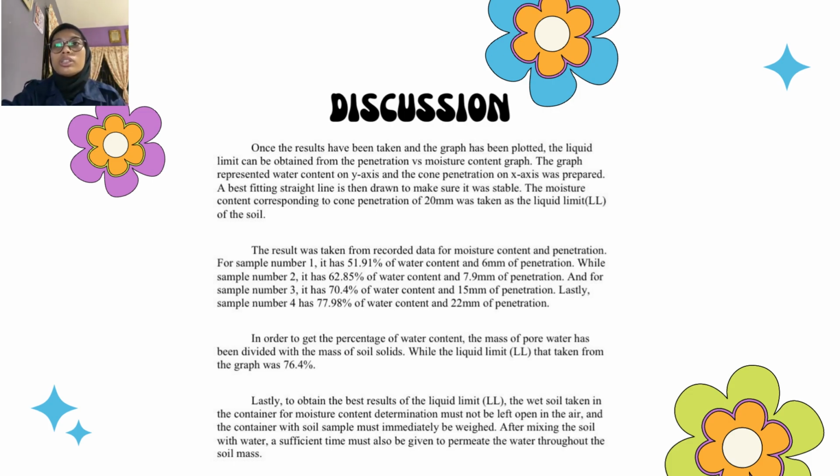In order to get the percent of water content, the mass of pore water has been divided by the mass of solid, while the liquid limit taken from the graph was 76.4%.